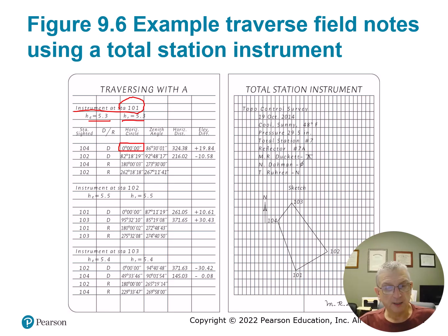And here again, typically we'll use point numbers so that they make sense. Commonly I would use a low point range for the initial, for my control points, like say 1 through 20 or 1 through 19, and start my Traverse at 20, or my side shots at 20.